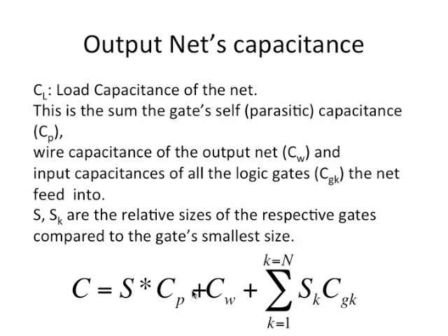It consists of its own capacitance Cp, and I have indicated a scale factor S here, because when I have a logic gate, we might have a logic gate with a certain size, but in the actual circuit we might want to use a larger or a smaller size. So suppose we choose the smaller size gate as a unit size gate. For that, let's say the capacitance is Cp. Then any other version of the gate when we instantiate it in the circuit will be some scaled version. We might scale it or we might not.